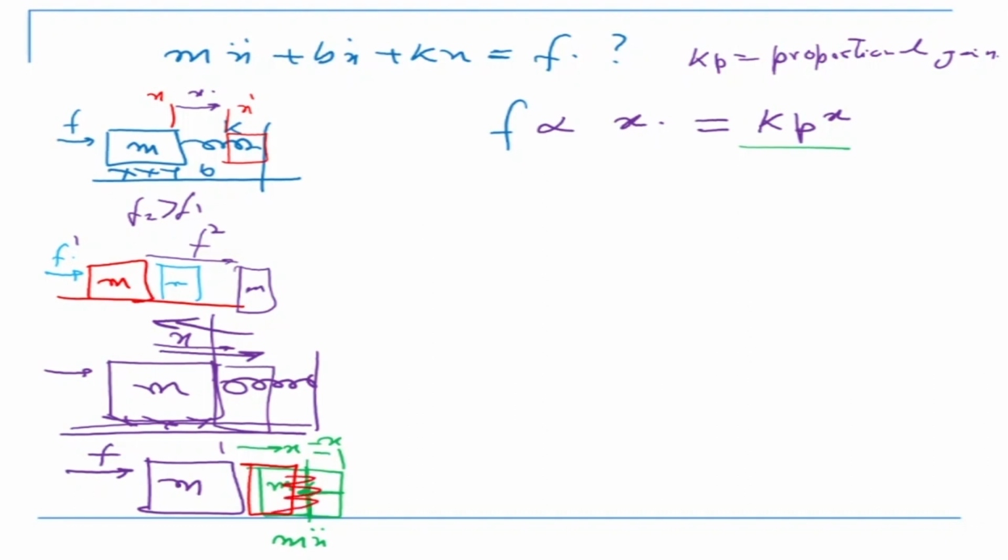So it is not being able to stop because of inertia, so we need to add another term. So the force must be proportional to x, which is okay, but it should also be proportional to x dot, the velocity, which is the incremental velocity, which is the difference between the point I want to go and where I am. So as you're coming nearer and nearer to 0, your force should decrease. Then it will go and stop at that. I hope you can imagine that point.